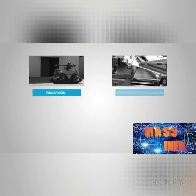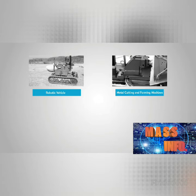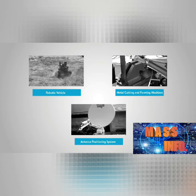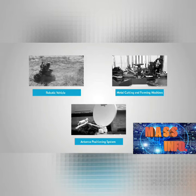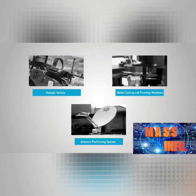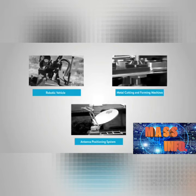Robotic vehicles commonly used in military applications with bomb detonation are controlled, or metal cutting and forming machines provide precise motion for milling, lathes, and bending for metal fabrication, or an antenna positioning system controls the precision in azimuth and elevation. As you'll learn in this lesson, servo motor applications are most commonly used in closed-loop systems, where precise position control is commonly found in industrial and commercial applications.